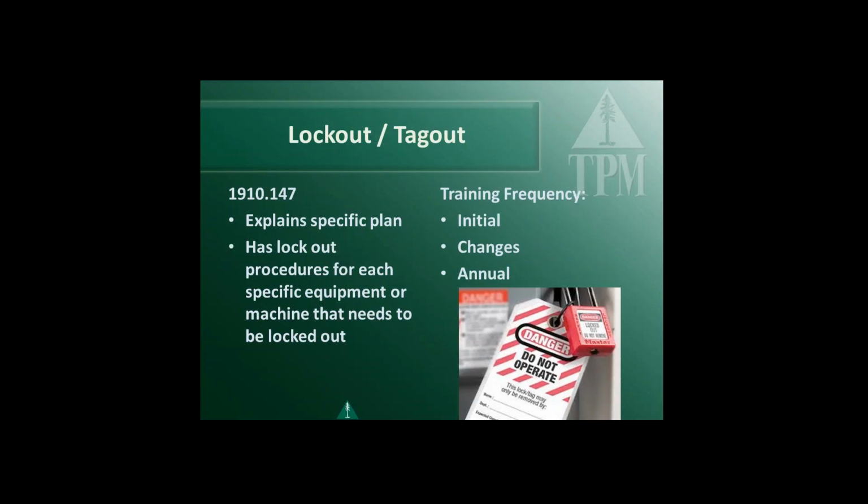So we modify our training, and that's why it's required annually, so we can add the changes into the Lockout Tagout program. So people are very, very aware of any changes, so they don't forget a step, which leads to catastrophic repercussions. Anybody that's involved in Lockout Tagout needs to put their lock on it. Well, I'm just handing the guy tools. Same thing as confined space, basically. If you're around it and you're exposed to it, you need to put your lock on it, and you need to be trained on it.